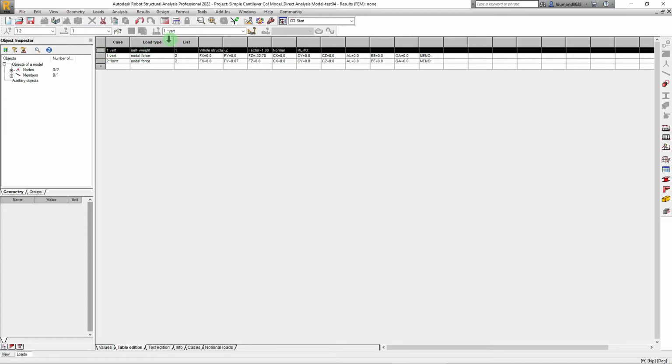Now notice I didn't even apply a self weight or anything like that to it. I didn't manually do this, but the software did it automatically, and it applied it to the vertical case in this instance, even though I defined my vertical load case as live. This is a quirk, I think, in the software, because it's not doing what the user wants it to do. Some of these things are automatic. You have to pay attention to it. I'm going to delete this for a second, okay?